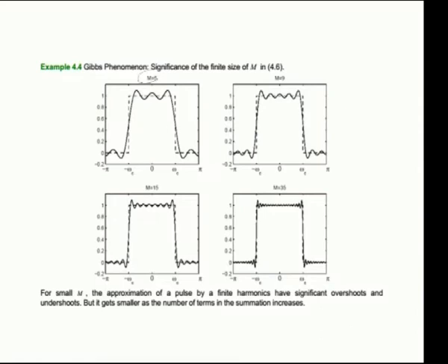So, by varying the constant value, m equal to 6, it shows the 6 peak values, right, the sine wave modulations. This is a magnitude response for the rectangular window. By varying the m value as 9, you can find the ripples. For m equal to 15, the number of ripples increases, and this is 35. So, more numbers. If you give n equal to 100 or 1000, it comes like a straight line. So, after executing the program, by varying this m value, we can check its magnitude response.